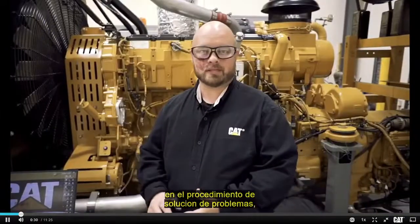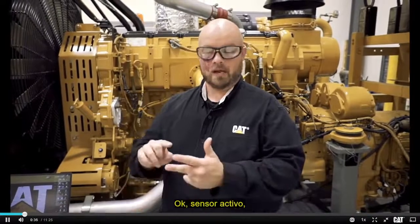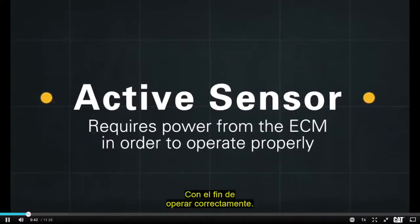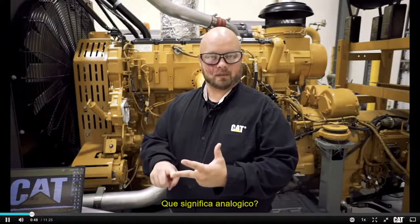Before we get too deep into the troubleshooting, I want to make sure we understand what we mean when we say active analog sensor. An active sensor requires power from the ECM in order to operate properly. In this case, we're dealing with a 5-volt sensor. Analog sensor, what does analog mean?